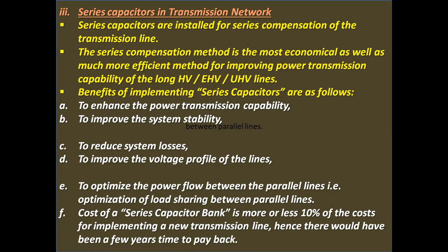Benefits of implementing series capacitors are as follows. A, to enhance the power transmission capability. B, to improve the system stability. C, to reduce system losses. D, to improve the voltage profile of the lines.